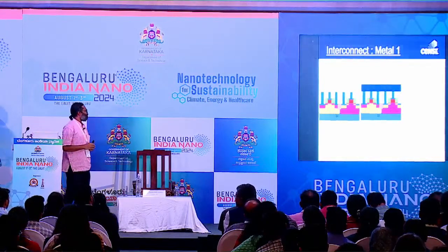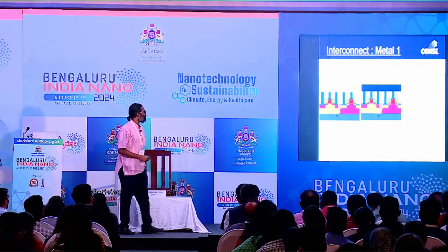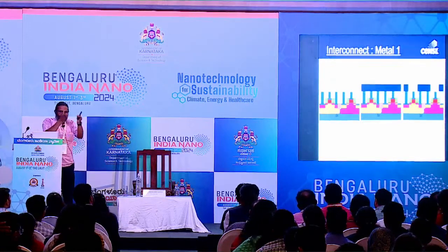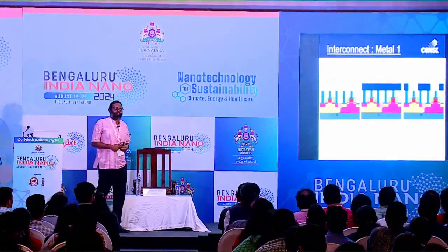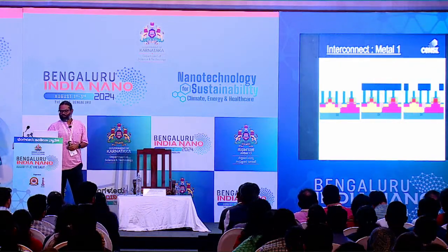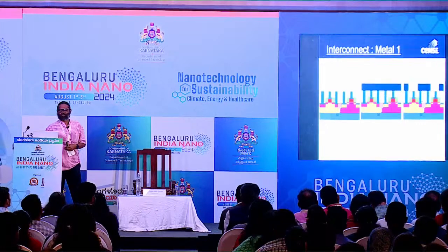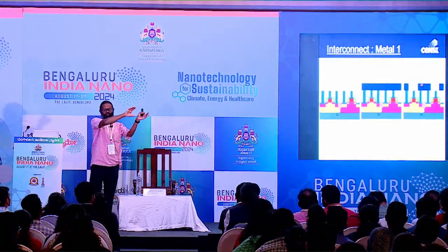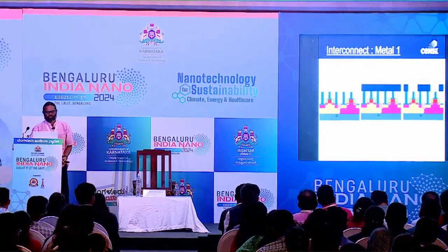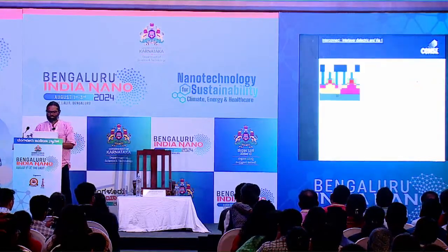We deposit a thin layer of metal, in this particular case aluminum, which is done using physical vapor deposition. Just the thin metal is there. And then you can etch the metal. I can remove it wherever I don't want. That's called etching. And now you can see these two transistors are connected, because this is a metal and this is a via, or a contact. So I said, vertically moving up, moving to the side, and then you can nicely make this contact. Similarly, I can put again an oxide layer and then connect the gates as well, which I'm not showing here.